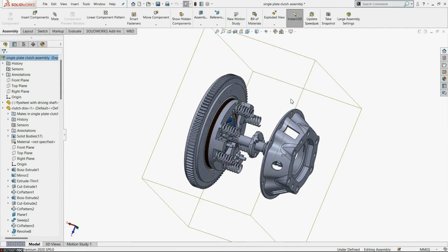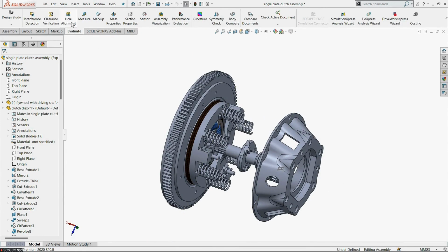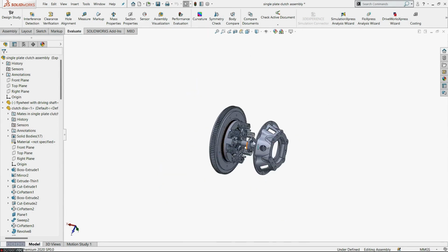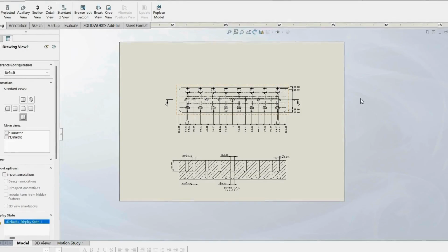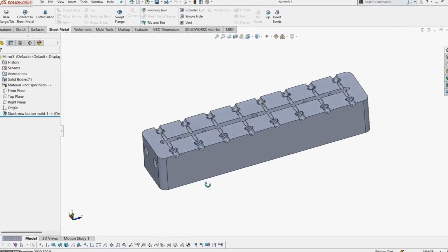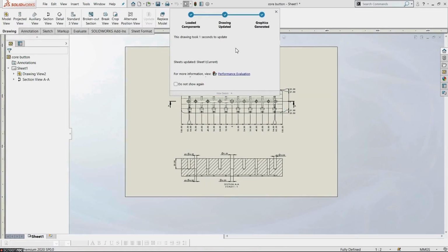Once you define each and every factor, starting from solid modeling to weldment, then you are going to learn about assembly. Assembly modeling is all about the importance of mates. There are three different types of mates: standard mate, advanced mate, and mechanical mate. Here you can learn how I can assemble the products and how I can create motions of the products under cam mate, gear mate, and universal joints.